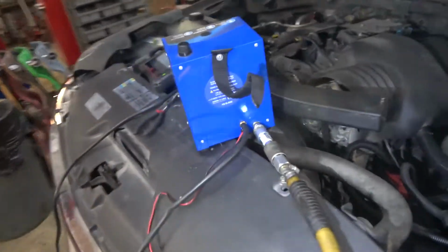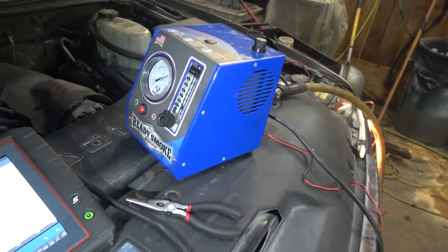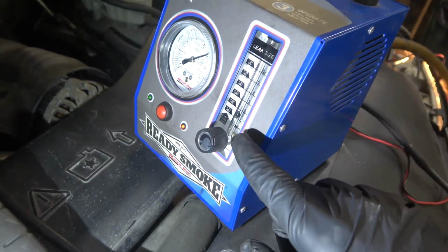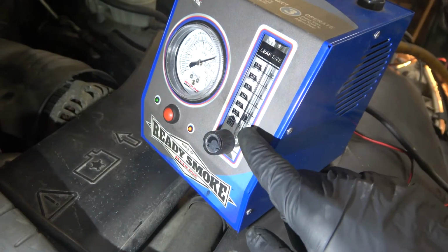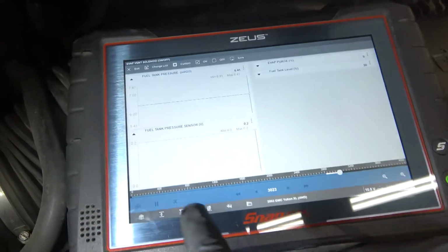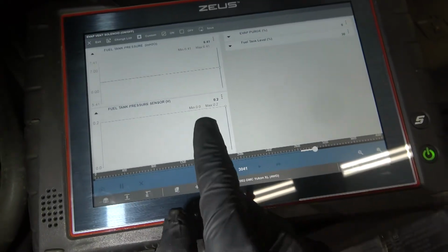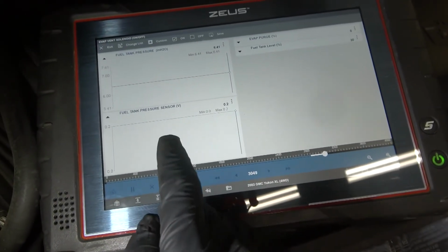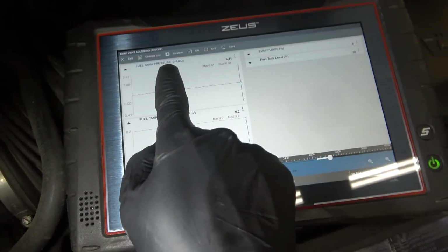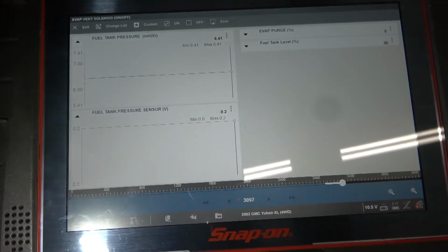sealed. Okay. Our problem is our fuel tank pressure sensor. Yeah, look at that. Our check ball went down even further. This is really good. Like, this is normal. Okay? But look at our fuel tank pressure sensor. Fuel tank pressure sensor is stuck at 0.2 volt. This voltage should change, okay? And this inches of water data pid over here should change. So remember these two data pids.